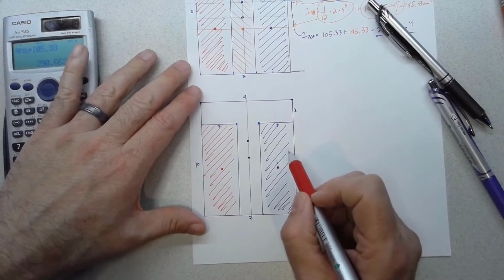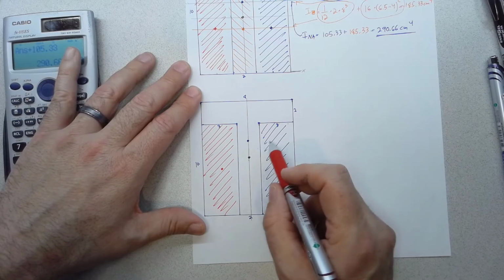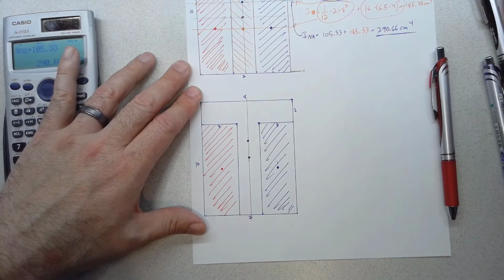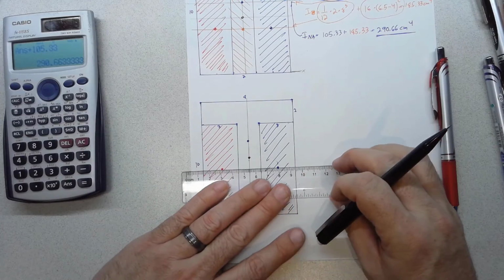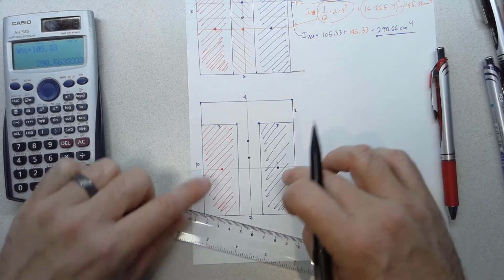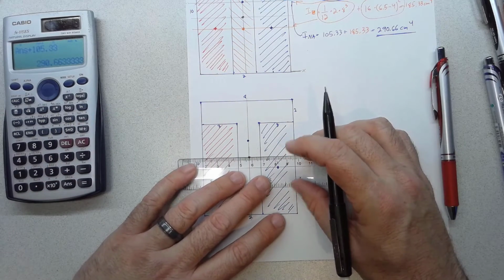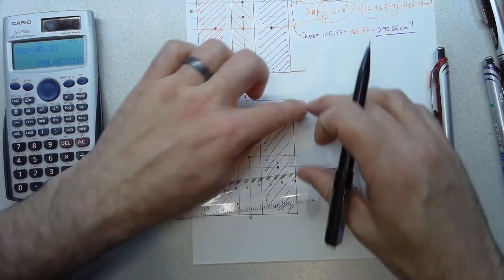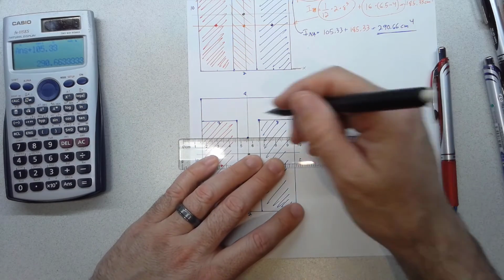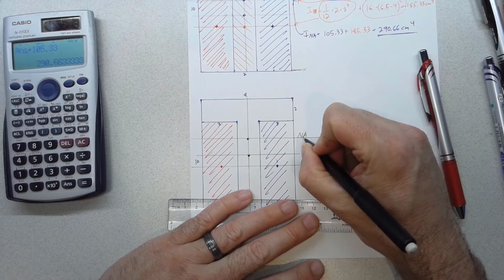So for each piece of this, when I'm looking at it for adding or subtracting pieces, I need to use the parallel axis theorem. Let's go ahead and do it that way. I just want to point out now that we have a bunch of different centroid distances and neutral axes. So this is a centroid distance for these two pieces we're cutting out. This is the centroid distance of the original overall 8 by 10 rectangle. And then this is the actual centroid and neutral axis of the final composite shape. So this is the one that we want to find I about.